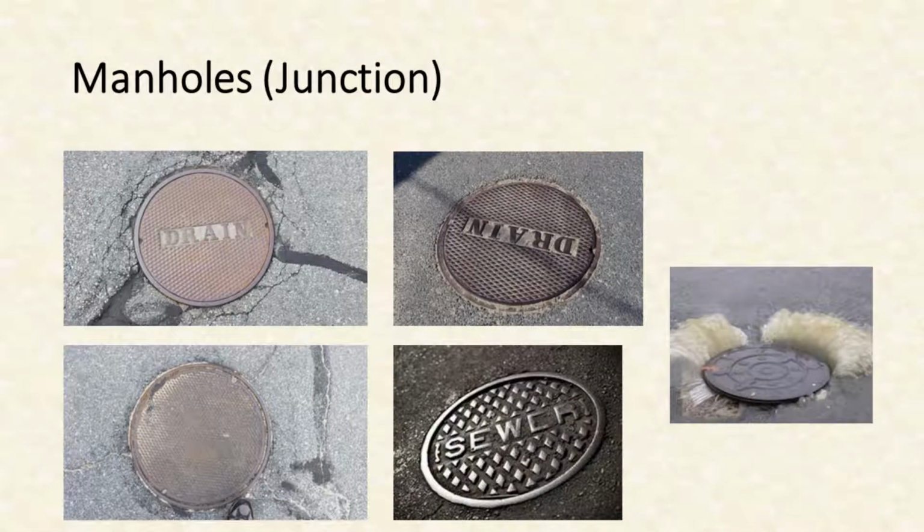Manhole structures are used by most utilities and are most common in sanitary sewer collection systems. Usually, one can determine which utility a manhole is associated with by a label on the cover. The word sewer, or the letter S, is used for sanitary sewers, and the words drain or storm is used for the stormwater structures. There are many unlabeled covers, and they tend to be associated with stormwater, but not always. It is not uncommon that an incorrect cover is used on a structure.